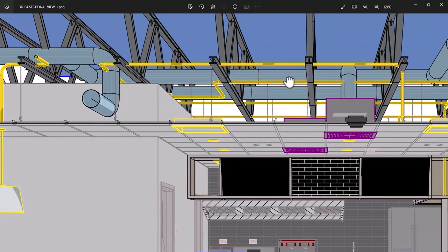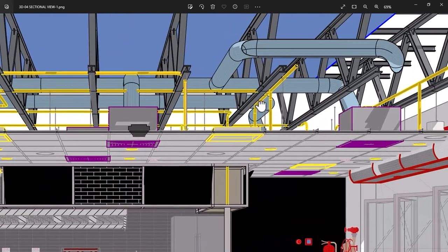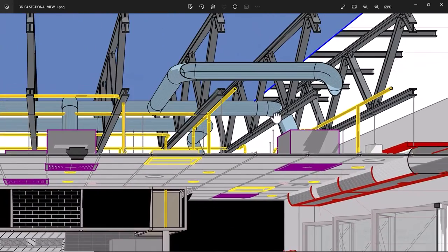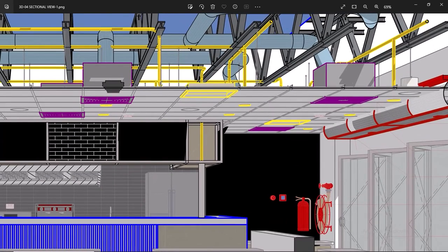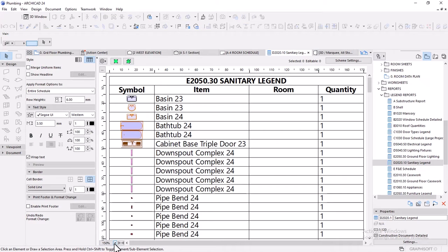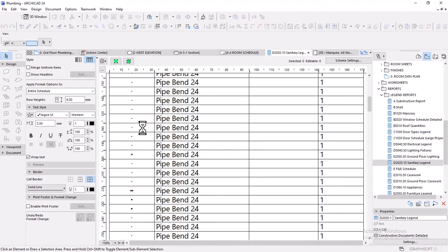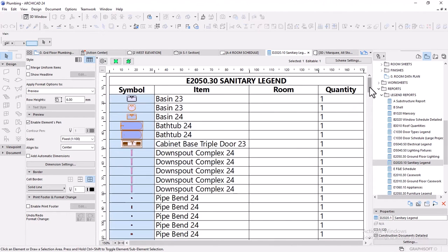and quantity takeoffs as well. You need to specify how many sockets are there, how many lights are there, how many tiles are there, how many windows are there. So this is one thing, quantity takeoffs as well for schedules, for construction coordination and so on. So you need to use proper objects for your representations of your drawings.